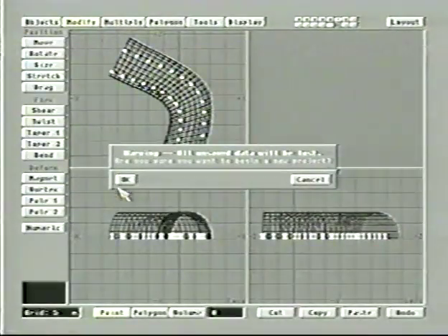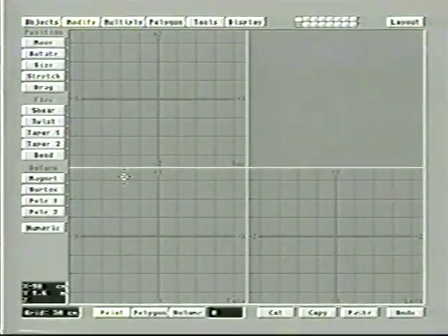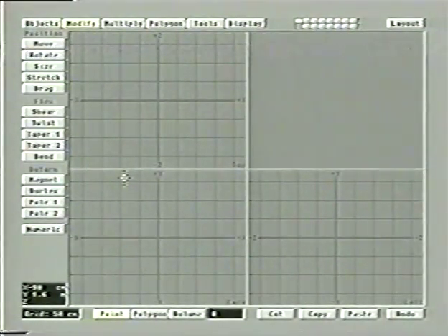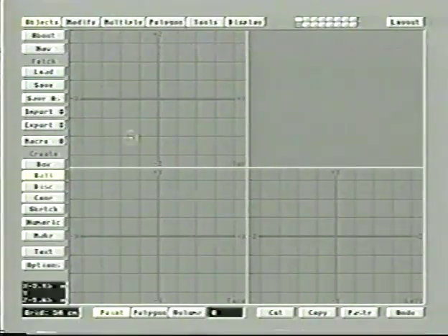Now, the way the Boolean functions work is they're similar in a way to the rail functions we've seen, in that the Boolean functions work with 2 different layers. You need 2 layers free. So I've saved the tunnel part, I've saved the pylons. Let me clear out everything with a new, Shift-N for new. And let me just give you a real simple explanation of the way Booleans work here. I'm going to make 2 objects. I'm going to make a sphere.